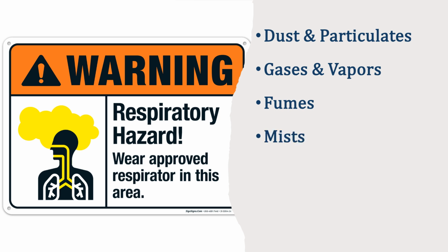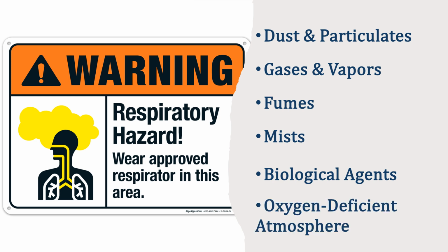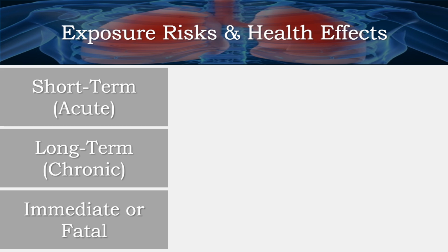Mists: chemical steam or spray paint. Biological agents: infectious agents like bacteria or mold spores. And oxygen-deficient atmospheres: environments where the oxygen concentration is below 19.5%. Exposure risks depend on the hazard's toxicity, concentration, and the duration of exposure, with immediate dangers like carbon monoxide poisoning and delayed effects such as asbestos-induced lung cancer.